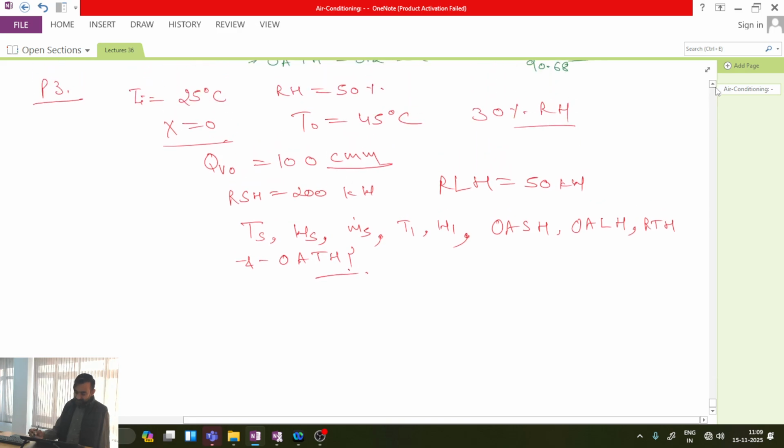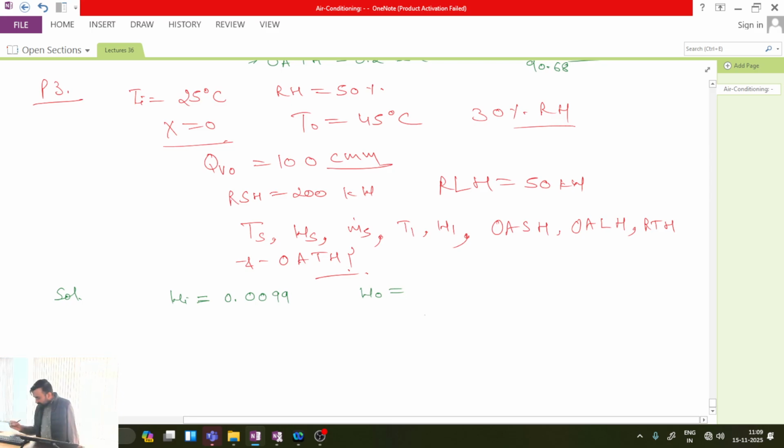Okay, so tell me first the value for Wi. How much is Wi? Already we have calculated in the previous question. 0.0099. W naught, WO, at 45 degrees Celsius and 30%, 0.018278. Okay. Other than that, what conditions typically?